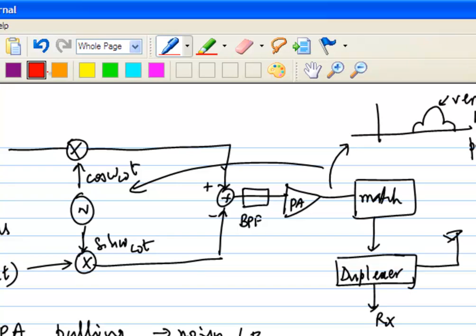So the assumption is that if we mix these two, we get some conversion gain. But why do you care about the gain? If we consider the entire feedback loop, because of the offset, I get some attenuation. What feedback loop are you talking about? This parasitic feedback. When you offset these two frequencies, you get attenuation, and there is a gain here that offsets that attenuation. What gain do you have here? Conversion gain. Actually, you don't care about conversion gain here, right?